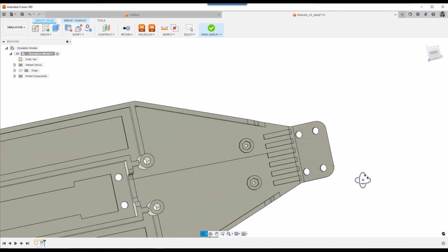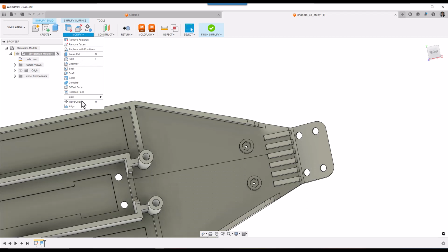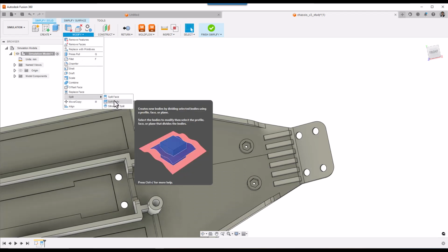from both the surfaces. Why is it needed? Because while we are creating the flow leaders and deflectors, we are going to assign equal surface thickness on either side of the part. If you want that thickness to be raised only on one side, probably you can just do the splitting only for one side of the body.